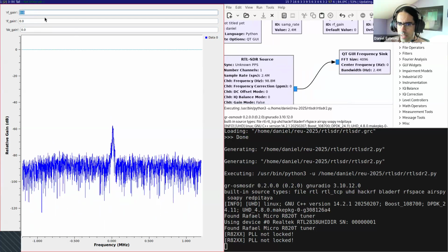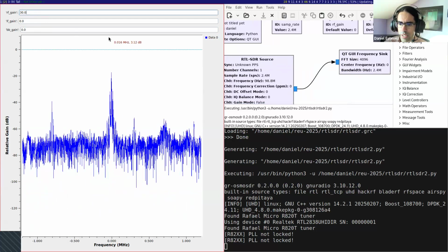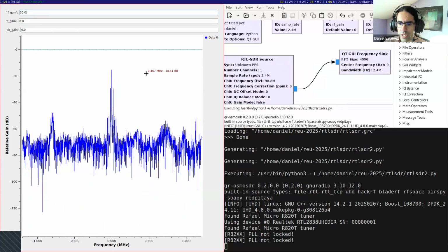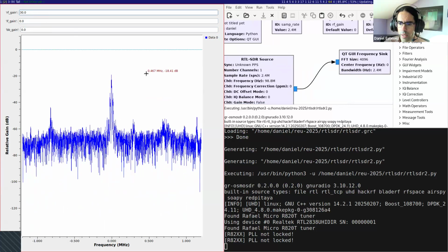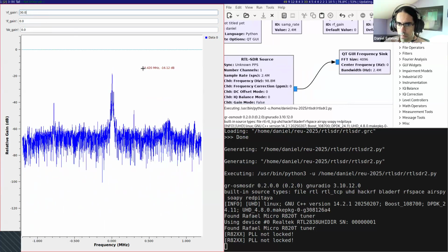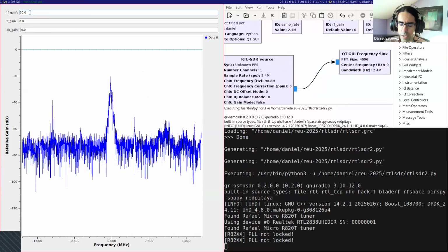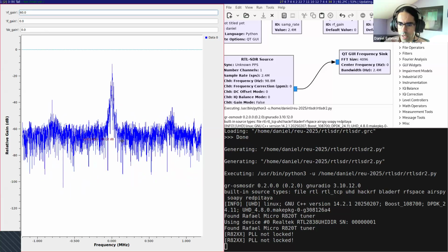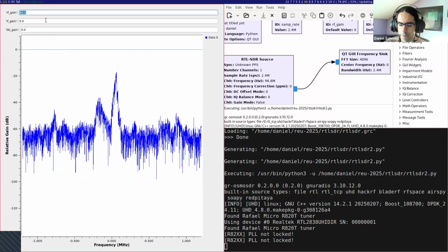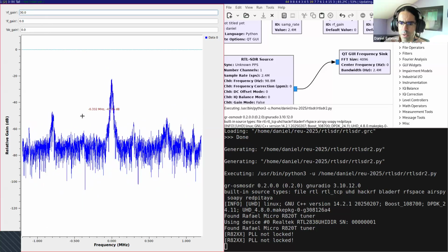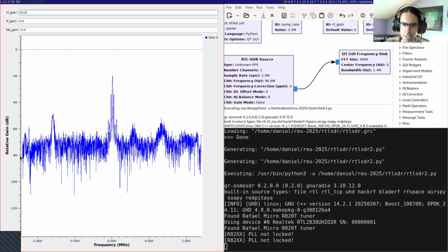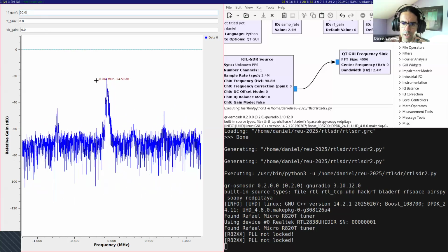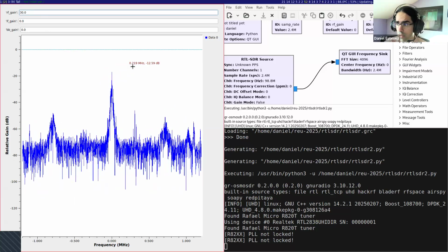And so we have learned that the only thing that matters here is the RF gain, and we can set it to 30 and see all the radio stations. And we could decide what's an appropriate gain in the same way that we did in GQRX. It's basically the same. And 30 dBs in here is the same as 30 dBs in GQRX. So if I go with 60, you can see that it is saturated. Maybe the thing which is not the same between GNU Radio and GQRX is the levels here in decibels, because of how things are normalized, really.